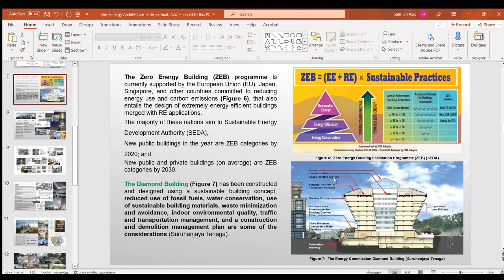And also a rooftop garden in the building, and a sloping roof for the photovoltaic solar panel installation, at the outer scale of the building facade. A tall tree line streetscape provides shading and a cooling effect, outside the building. Glass entrance canopy with water elements as well, and also a pedestrian walk outside the buildings. And a light shaft, low-E glass, which is double glazing used by the buildings to decrease the internal temperature by the natural light.